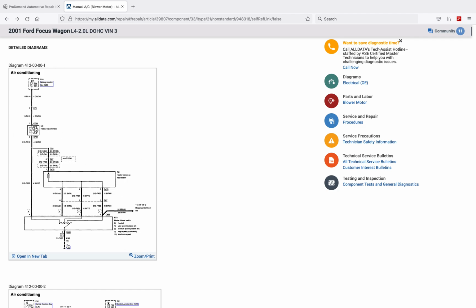So we go to low speed. I turn my dial from off to 1. I want the fan speed to be low. If I connect this as a ground point, remember we have to have potential energy. Power is here. I connect this G14 to ground. Here we go. This is going to be my path.